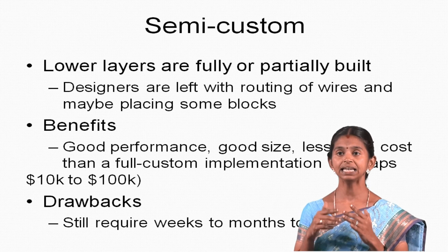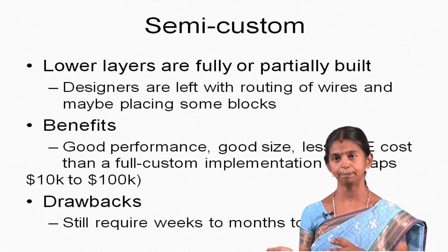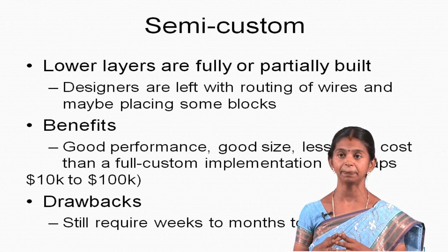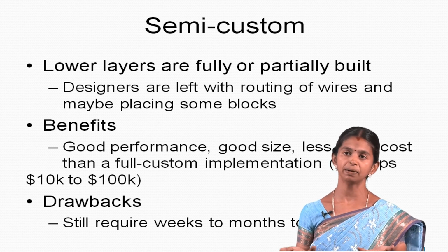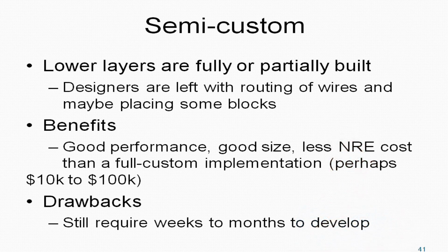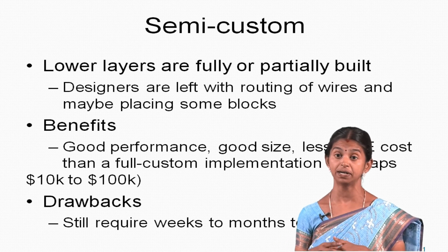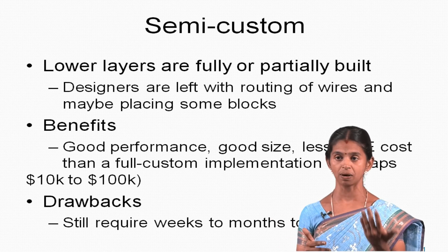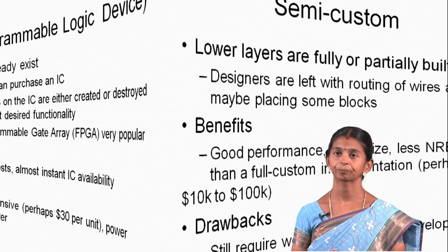Semi-custom: lower layers are fully or partially built. Designers are left with routing of wires and maybe placing some blocks. What are the benefits we gain from semi-custom? Good performance, good size, and less NRE cost than a full custom implementation. Drawback is that it still requires weeks to months to develop.